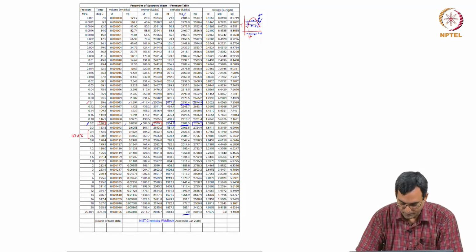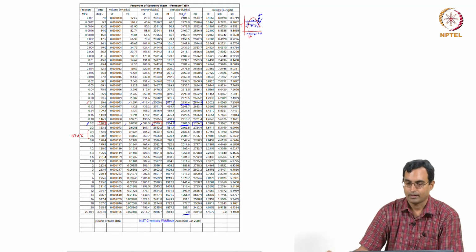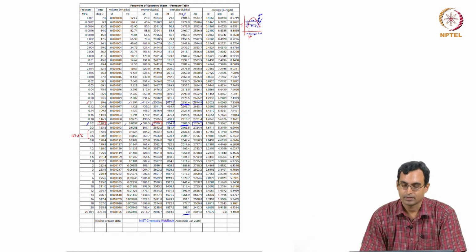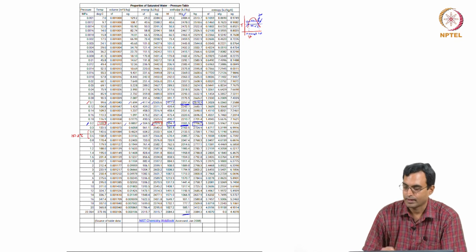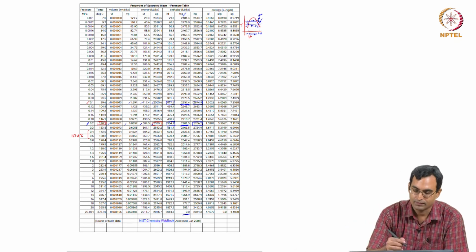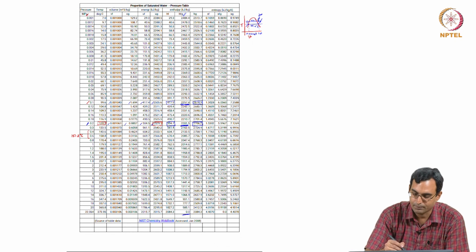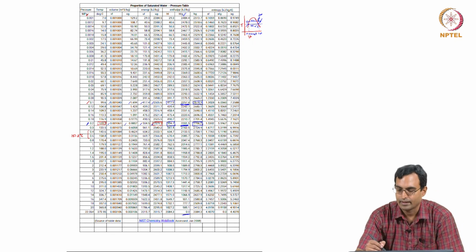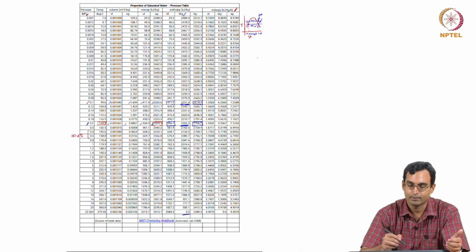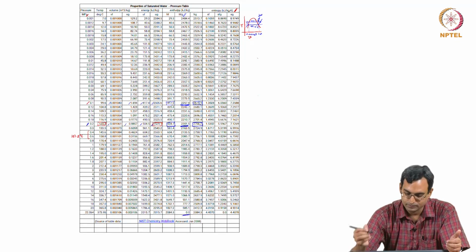So, we are already familiar with the steam tables. So, I have this open in front of me. When we were looking at the values on steam tables, we looked at the pressure and temperature tables for saturated liquids or saturated vapor. So, we looked at all of these columns, essentially we looked at pressure, temperature, volume and so on. So, the entropy for steam and water is also listed here. We had not used these values so far, but now we know how to use it because we can just read the table, the values of the table for a given pressure and temperature condition.